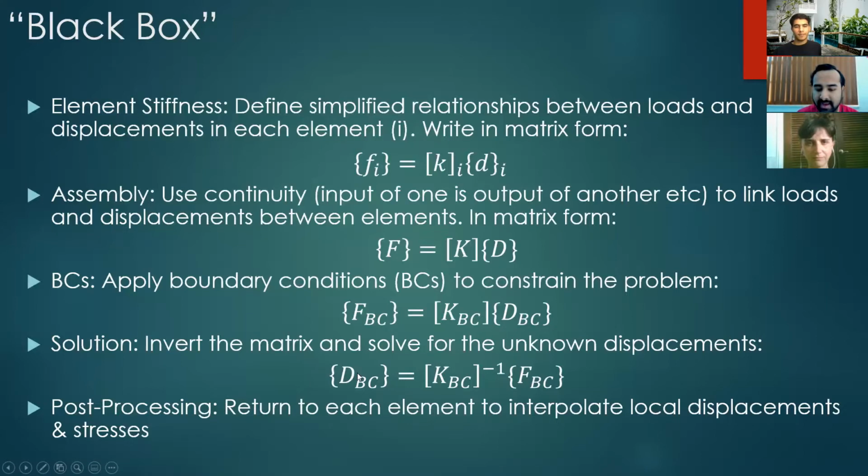And now I can solve for displacements by just inverting the stiffness matrix and multiplying it by the forces I know. And voila, then you just post-process. So you can turn your displacements to strains. From strains, you can figure out where your stresses and such are, because now you also know the material properties. And from there, you report and improve.